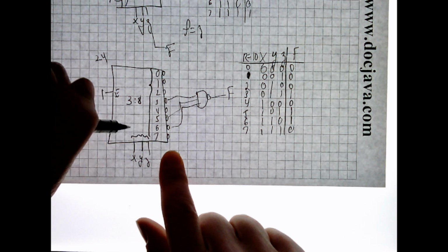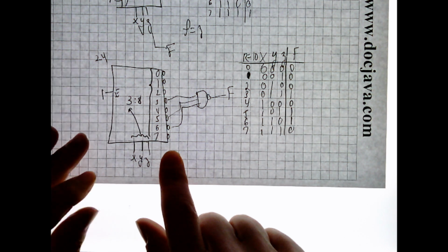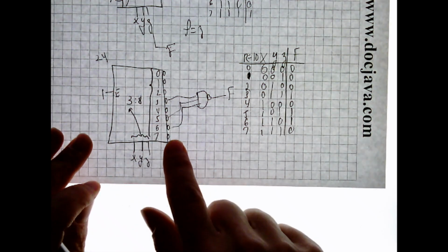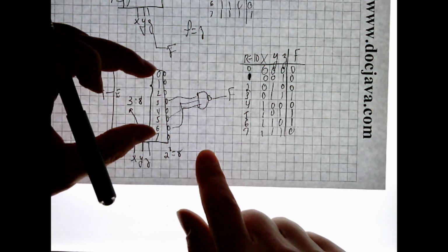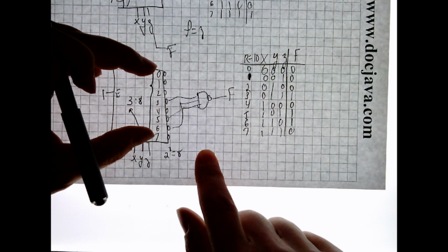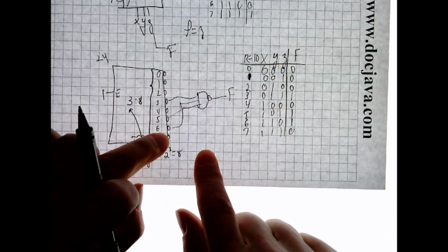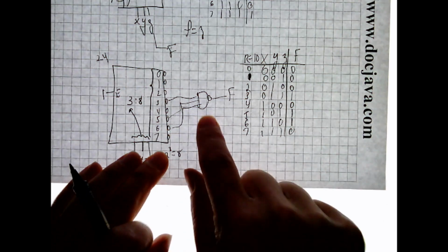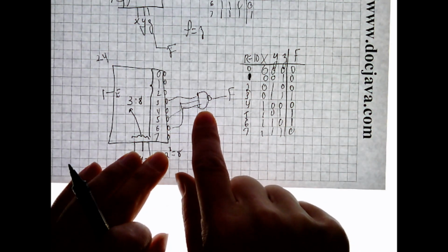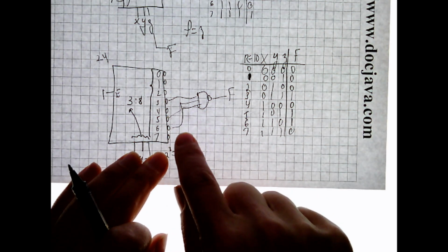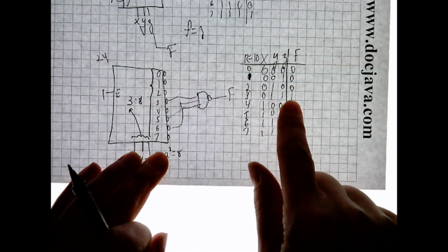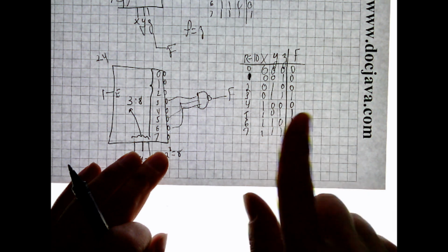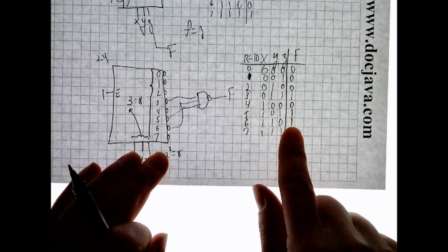And you can see there's the 3 selectors being used. So that's 2 to the 3 outputs, right? 2 to the 3 equals 8, that's why you got 8 outputs there. And so then they're all inverted. And then if you want to throw on the NAND gate into lines 3, 5, and 6, then you're going to get row 3, row 5, and row 6 to be asserted as a 1. Any questions about that?